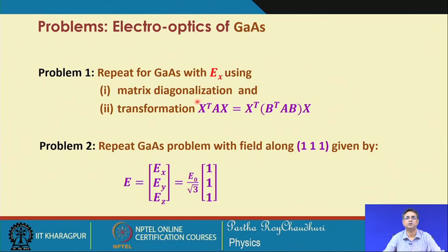We can also calculate that for the case of E x. These situations give more insight into the various configurations that can be used for this electro-optic crystal, and to compare which configuration is more useful and requires a lower half voltage.